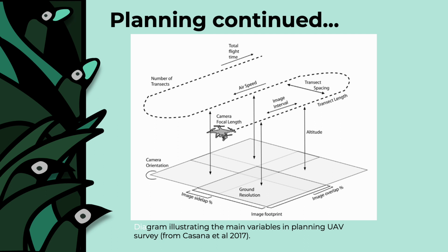Most UAVs are equipped with sophisticated instruments to ease flying and to reduce crash risk. This includes a global navigation satellite system, barometric altimeter, compass, collision avoidance sensors, and a gimbal to reduce image motion distortion. Flight plans should be made in line with Transport Canada regulations prior to the survey to reduce hazards should something go wrong during flight. This might include the loss of sight or control of the aircraft and mechanical failure.